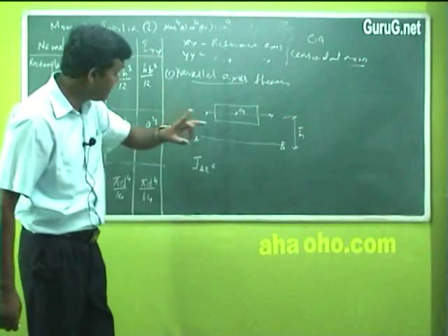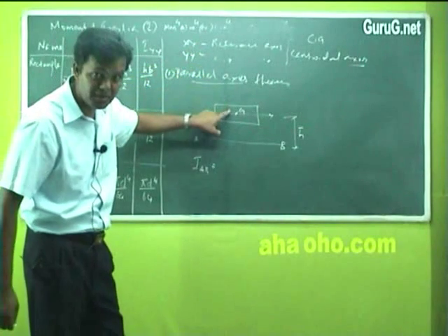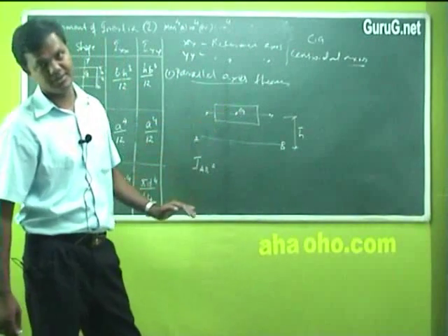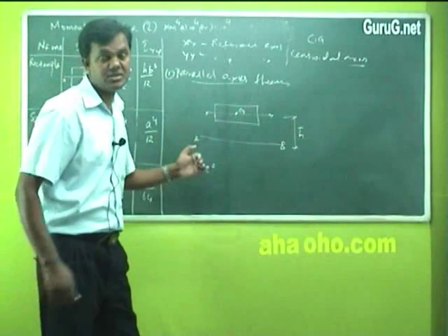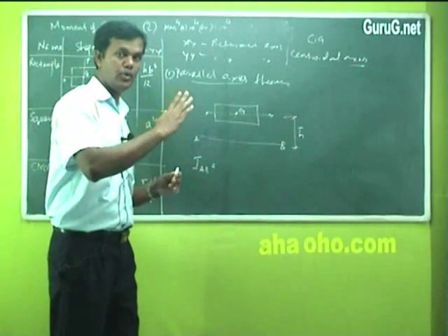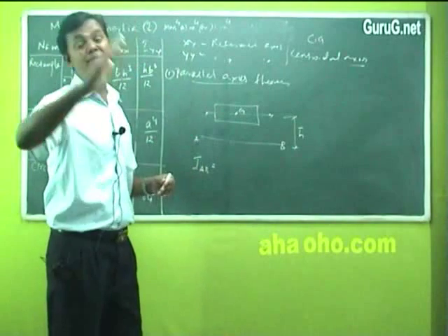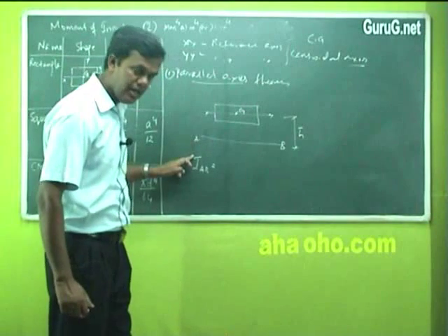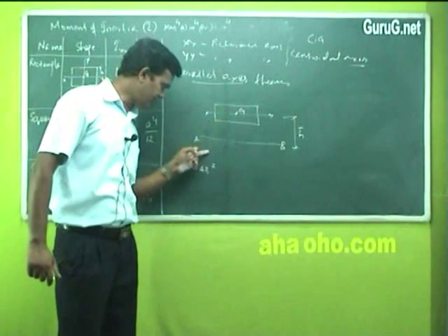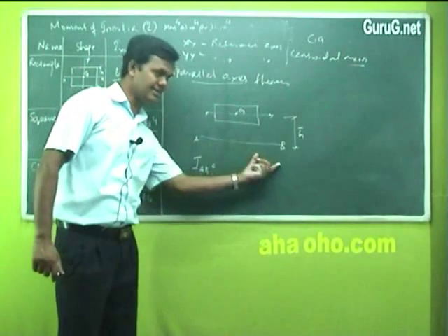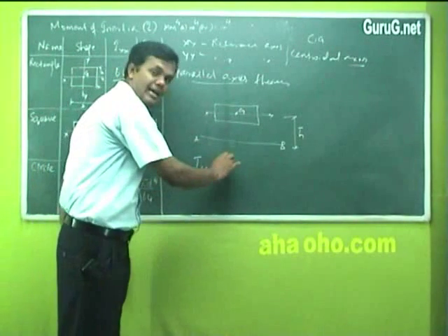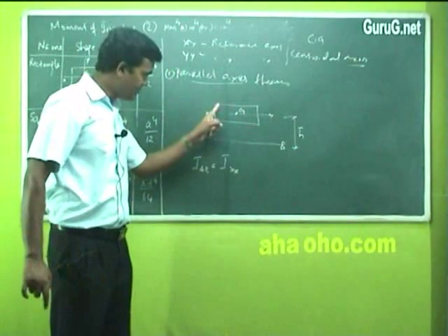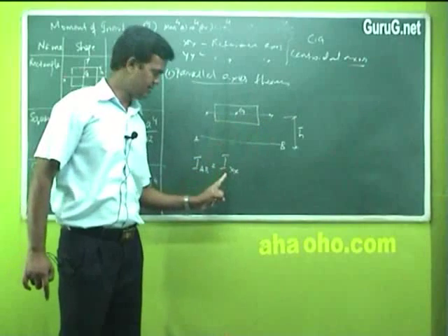Okay, centroidal axis means x-axis and y-axis for this particular body. This is a different reference axis line which is far away from this centroidal axis. You have to understand, because it is the second moment of area. I told you it is force into perpendicular distance, again multiplied by distance. Is it not? So the moment of inertia of this body with reference to this reference axis AB is given as the moment of inertia of the body with reference to that particular axis xx, Ixx.